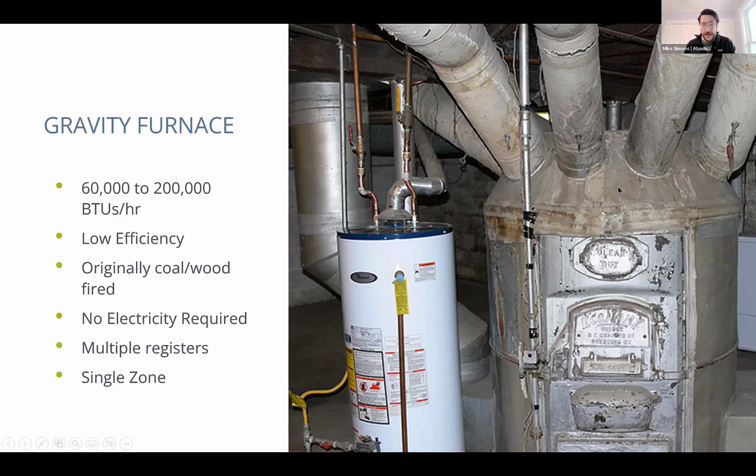Somewhere on the first floor would have been a grate or a hole or a vent in your floor, and then they would be connecting ductwork back down into the basement, into this furnace. This is just heating up the air. Cold, dense air falls down into that grate and then into the furnace, and combustion is taking place. It's warming up the air, making it hot and buoyant, and then all of that warm air is traveling up into each of the different rooms.